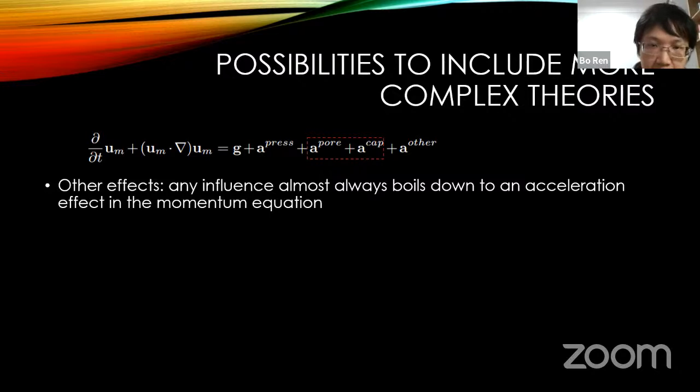Till now, I just talked about Darcy's law, but this approach can extend to other more complex theories. If we look at the momentum equation, we can see that any effect will influence the fluid particles as an acceleration effect. It will appear as a different acceleration term or more acceleration terms. You can just add them in this momentum equation.